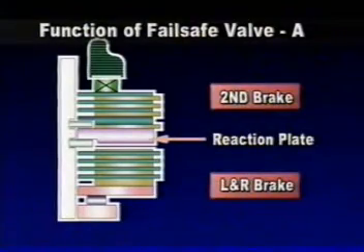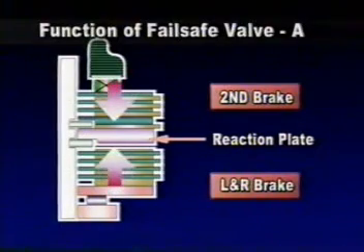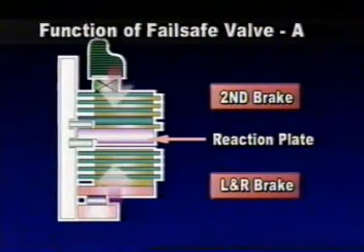Since those two above-mentioned brakes share the reaction plate, they cannot operate simultaneously in any case. If they operate simultaneously, it may cause automatic transaxle interlock and serious damage to the mechanical system, including the inside bearing of automatic transaxle.